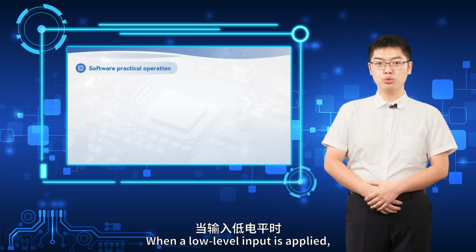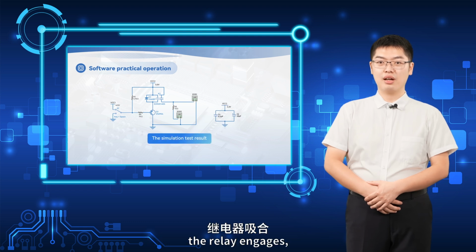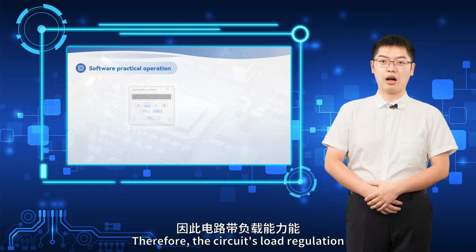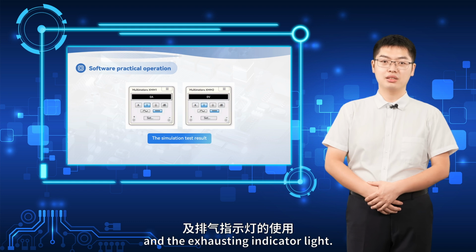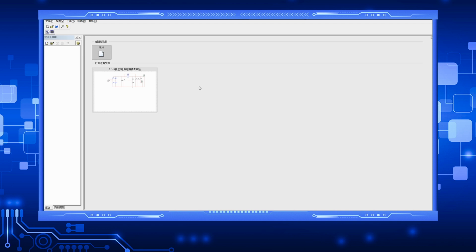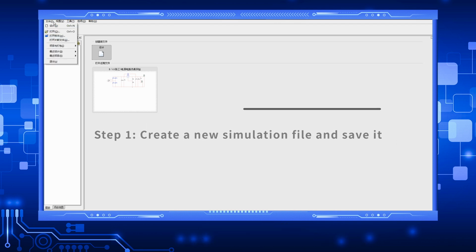When a low-level input is applied, the transistor is in saturation mode, the relay engages, and the output voltage is 5 volts with an output current of approximately 333 milliamperes. Therefore, the circuit's load regulation is sufficient for the small exhaust fan and the exhausting indicator light. Now let's learn how to draw a simulated circuit. Step 1. Create a new simulation file and save it.